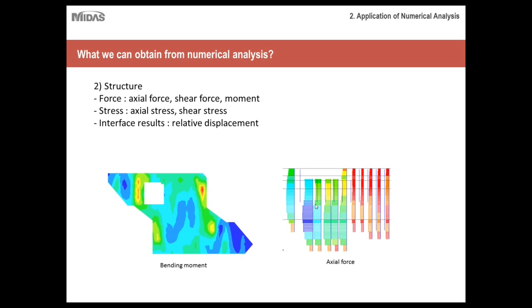And then here we have the axial forces for a group of pile elements. As you can see, the program clearly delineates axial forces that reach a certain range. So these piles here to the right might be of interest to the engineer who's studying it. You might want to see why exactly those piles receive X amount of axial force as opposed to these ones. So this works for 3D geometry as well.